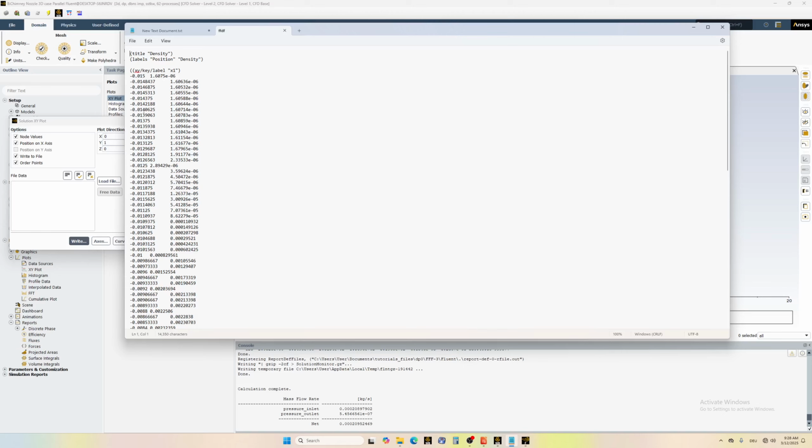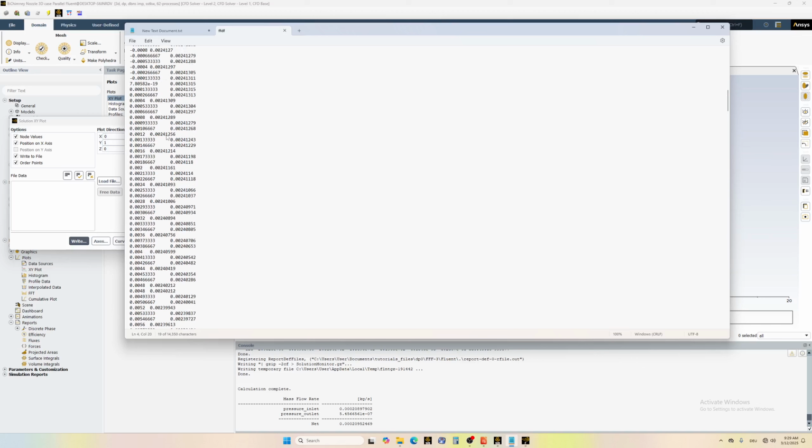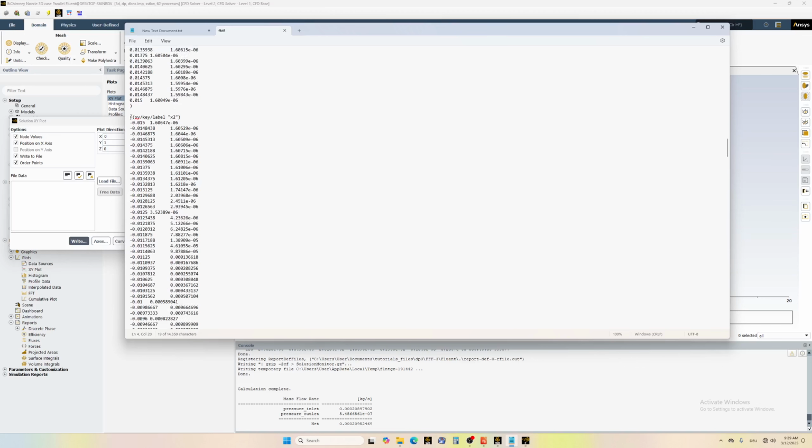Here you have to be careful, because on the left side is the length dimension in meters, and here is the density in kilograms per cubic meter. So you need to transform this to get other units like atoms per cubic centimeter. Be careful about this one. Here you will see it is at x1, which is 1 millimeter above the nozzle. This is the profile. If you go down, here is x2 and so on. Depending on how many line outs you have, you'll export all of them.